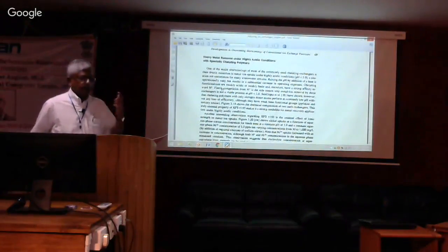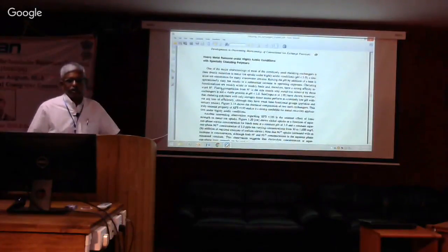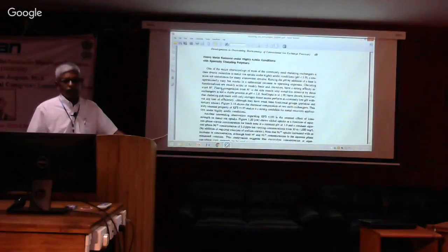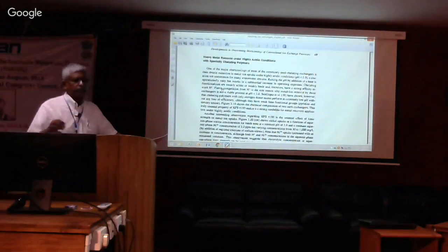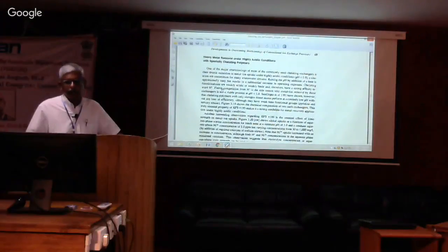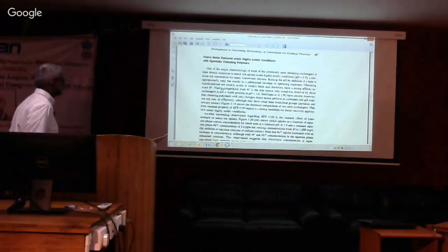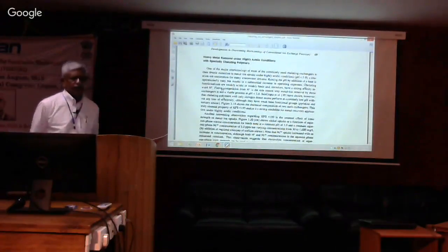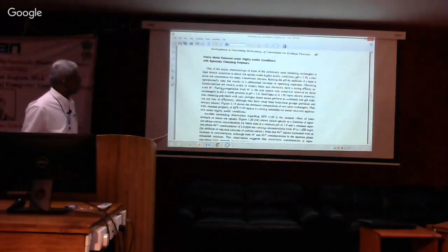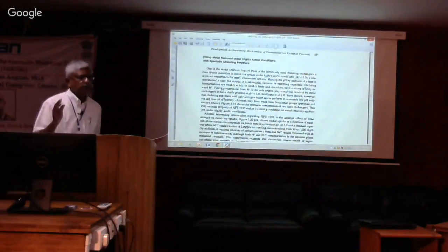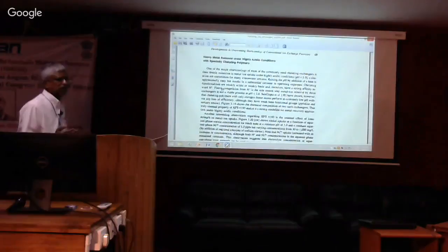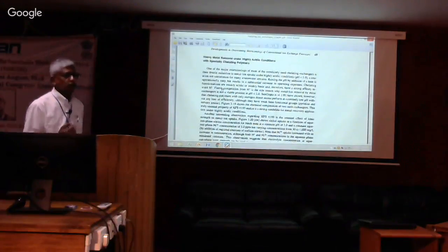not work because, as we saw, the swelling and shrinkage would be so much, and this resin would be compromised, because a strong acid would destroy some of these sites or some of the backbone of the polymer also. So if you have a situation like this, then a regular chelating functionality may not work. You have to look at some novel chelating functionality. Okay? So, for example, strong acid will not work. But even a regular weak acid like iminodiacetate or carboxylate will not work.